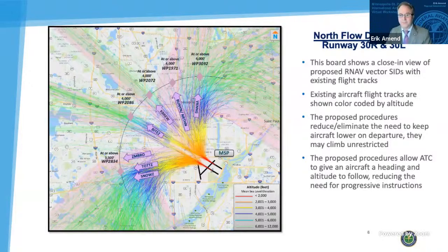All right. And so those points to the north, those diamonds, represent also altitude restrictions that the pilots need to comply with to ensure they climb above certain airspace below them, like Anoka to the north and Crystal to the northwest. And so this will ensure they keep climbing above these certain airspaces to ensure our separation standards, now that we won't have our VOR anymore, because our VOR gives us our crossing restriction.